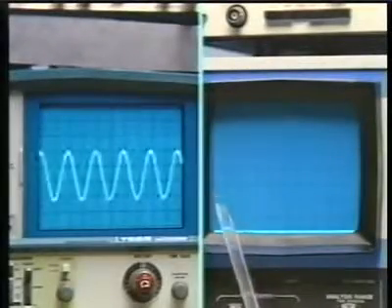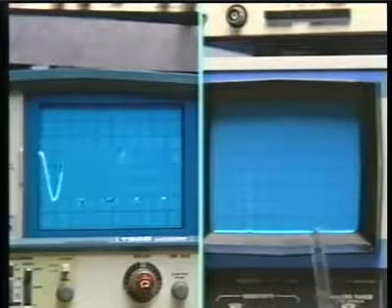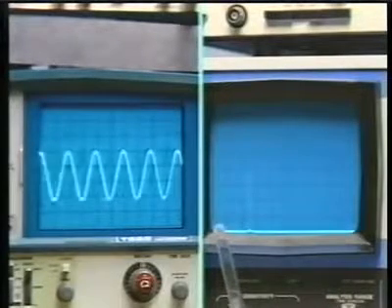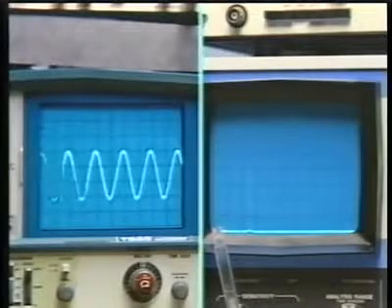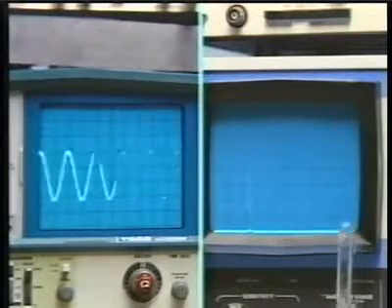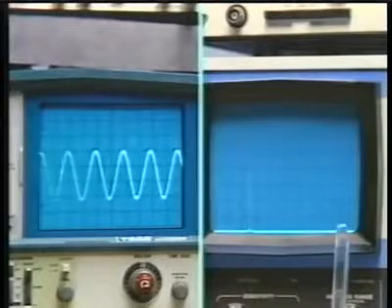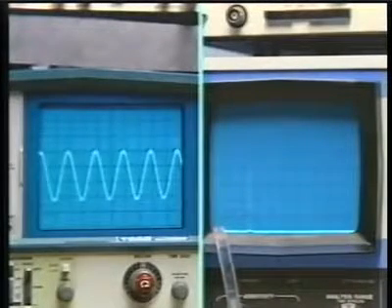And the vertical axis is the amplitude. The horizontal axis is frequency, and as it's set currently, the frequency axis goes from DC, 0, up to 2 kilohertz, and that, of course, can be varied on the spectrum analyzer.